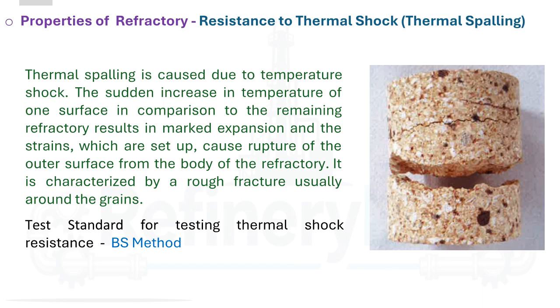Then comes the shock. The specimens are pulled out of the furnace and left to cool in open air for 10 minutes. After cooling, they are placed back into the furnace, and the cycle begins again: heat, hold, remove, cool, repeat. After each cycle, the specimens are inspected. Engineers look closely for cracks, chipped corners, or any signs of weakness. Sometimes they will even pull on the specimen by hand or with a rig to check its strength.